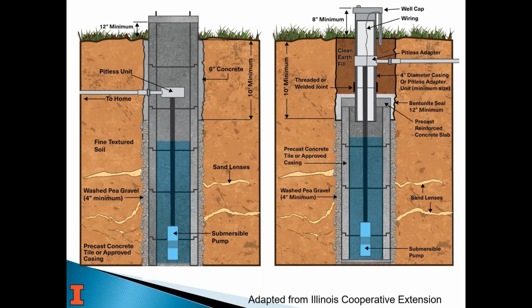This is a bored well, so that adds more volume, because the water can also fill into where those rocks are, and sand and gravel they may put around the well. But it's seeping in at each of the seams, and here they've got a submersible pump down further below, and you can see where the water level is, and that's also the water level in the water table.